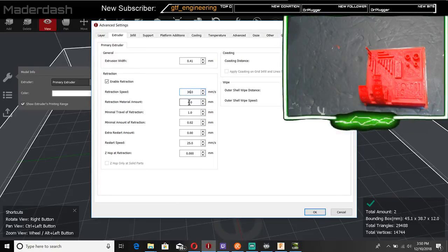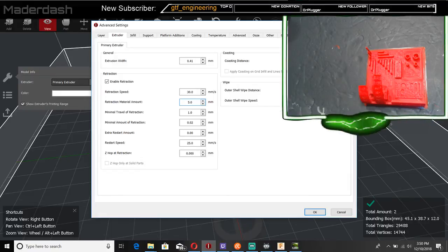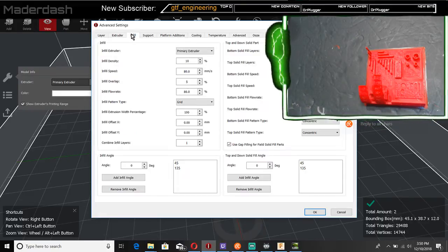Retraction material amount, let's go down to, let's say 5. Restart speed, 35 should be fine. Coasting distance, 0. Wipe distance, we'll leave the wipe at 0.